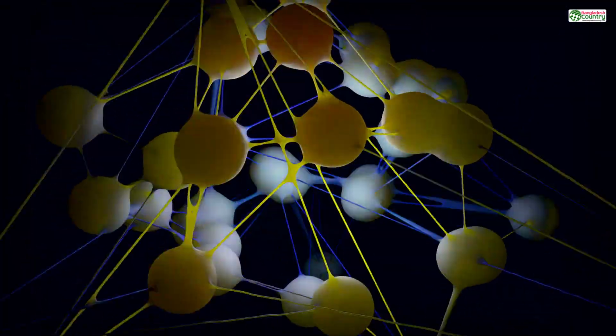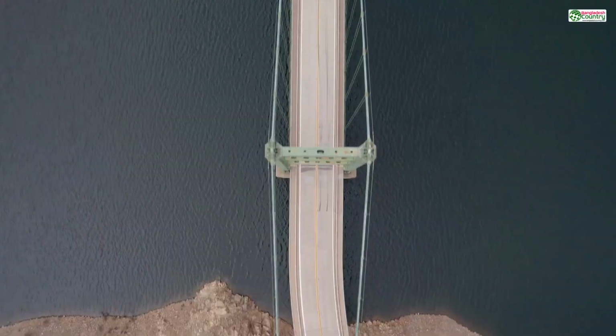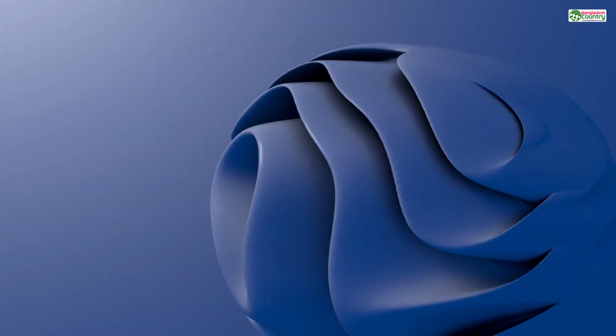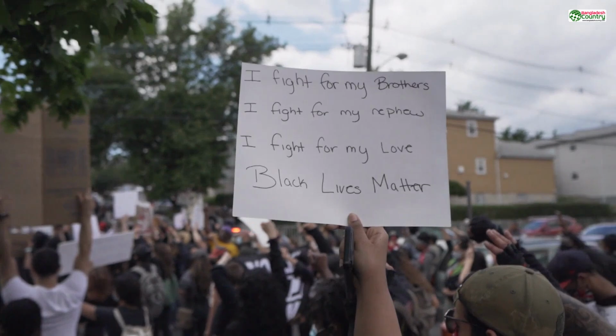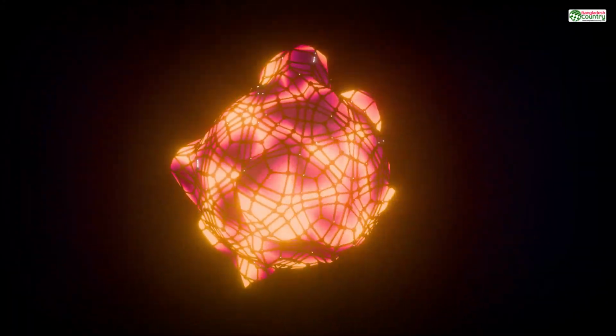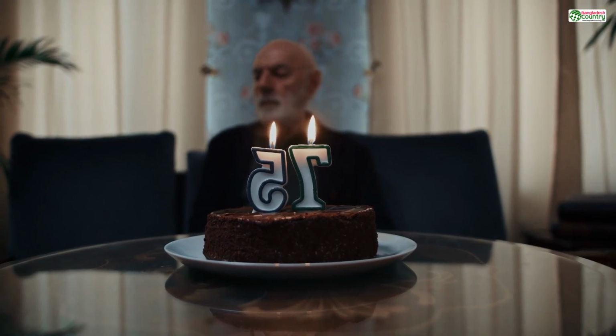Gyroid is a mathematical marvel. It's a 3-dimensional, infinitely continuous surface that looks like something out of a sci-fi movie. It has no straight lines. It's all smooth, flowing curves that create a wave-like internal structure. The reason it's so amazing is that it provides nearly uniform strength in every single direction. It doesn't matter if you push, pull, or twist the part. The gyroid infill resists the force almost equally. It's also fantastic at absorbing impacts. It's one of the most advanced and effective infill patterns you can choose for high-performance mechanical parts. It takes longer to print, but the results are simply on another level.